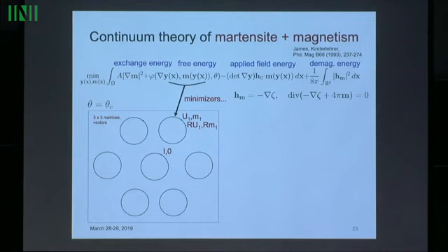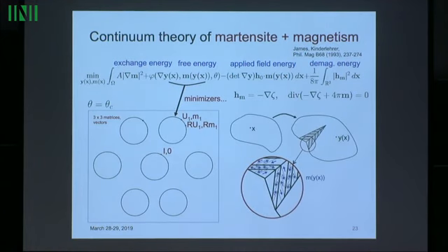I'll tell you about what this means. Now, also there's a symmetry issue. And maybe I have that here. Okay, the schematic is then what we expect: we have a reference configuration. We deform it with this deformation y of x. On the deformed configuration lives this magnetization, and it can have domains. So we can have martensite plates like we've seen before. We can also have, within those plates, a vector field which represents the magnetization. So it's a bit complicated, and then there's the symmetry part.